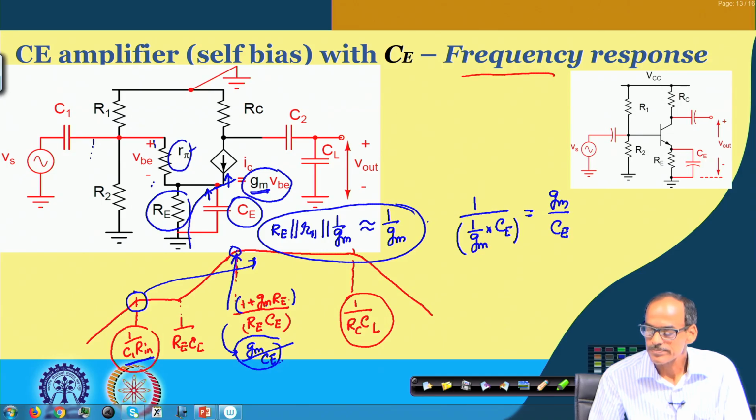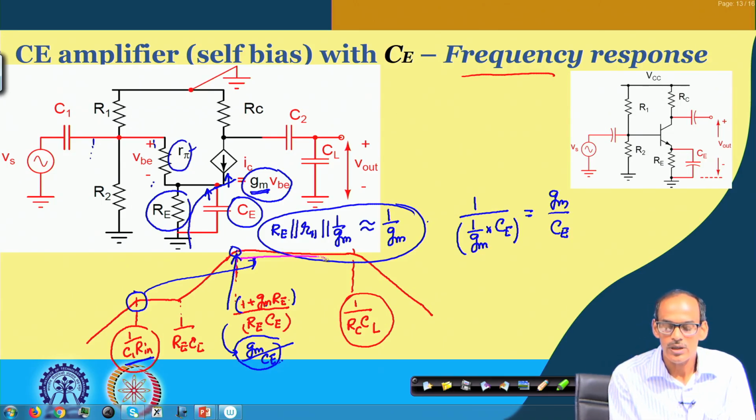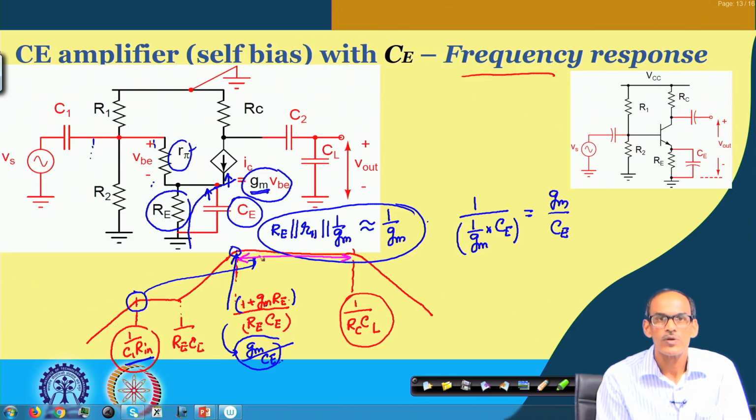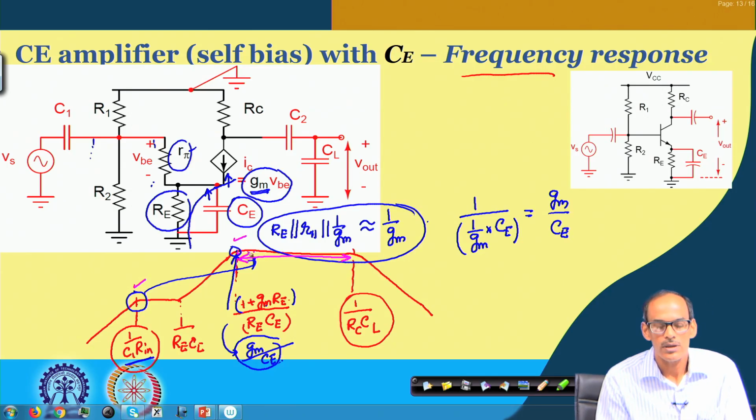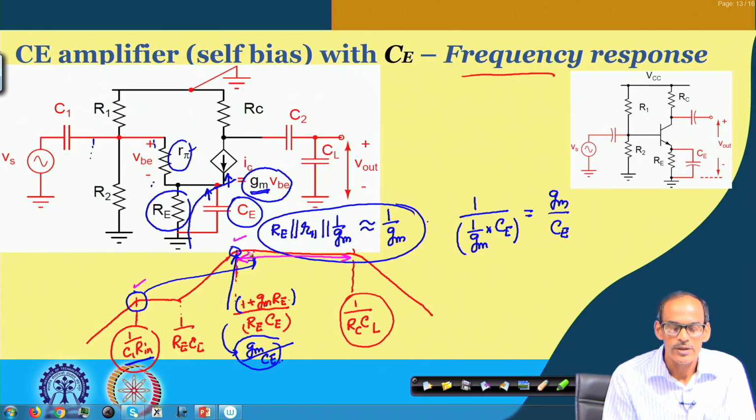That is because you may remember that our main purpose is to get an amplifier having a good gain. So, this is our main frequency band, and a wider band is better most of the time. If one of them exceeds the other, whichever is lying on the right side defines the lower cutoff frequency.